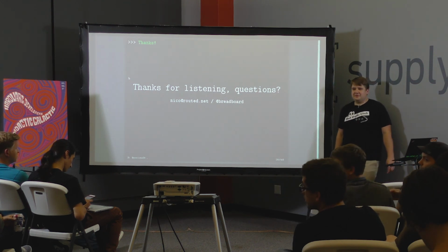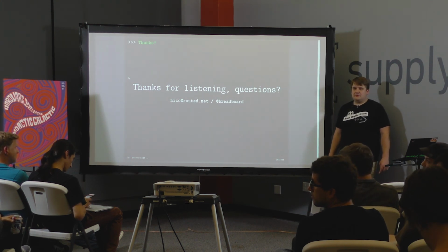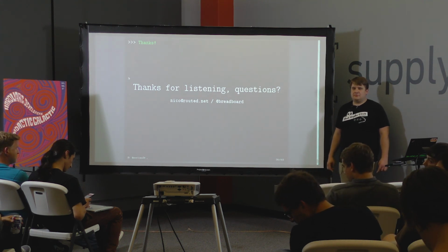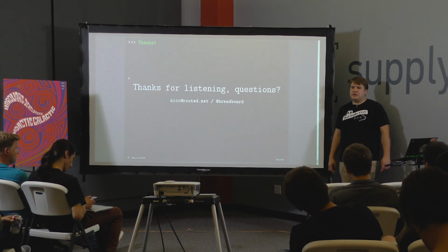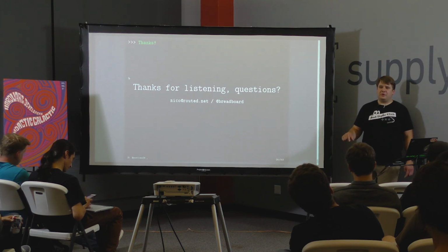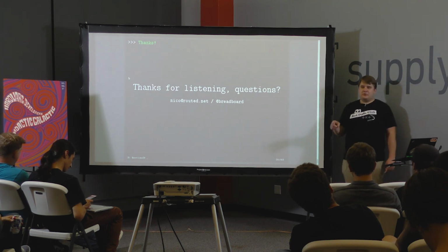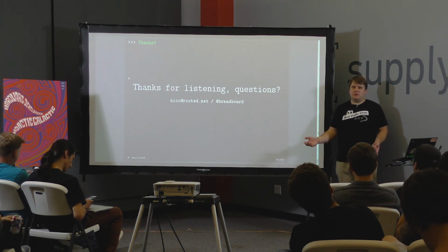So you mentioned running cold, letting your components cool down below -40. The behavior of the components is specified down to -40. Do they ever attempt to characterize what happens when you get colder than that? And have you run into any problems? The answers we get are either no, or a no with an expletive, or they just don't reply. Basically, characterizing below -40 will require one of two things: either for you to do it, or to pay somebody a lot of money to do it. But basically, you have to validate this stuff and you have to accept a certain amount of failure.